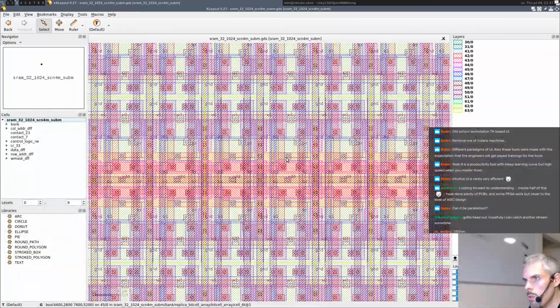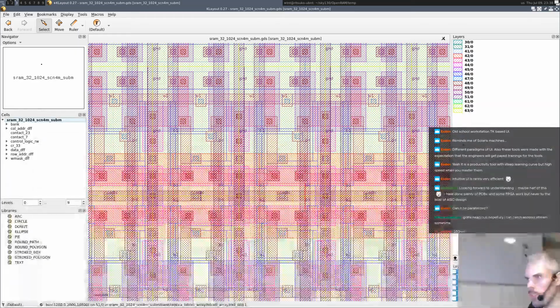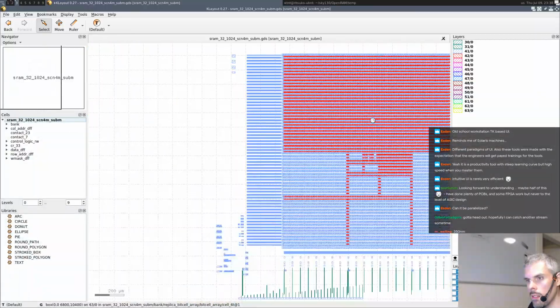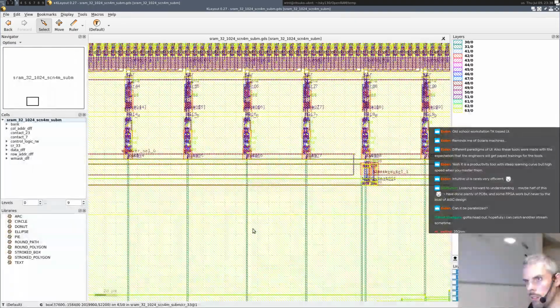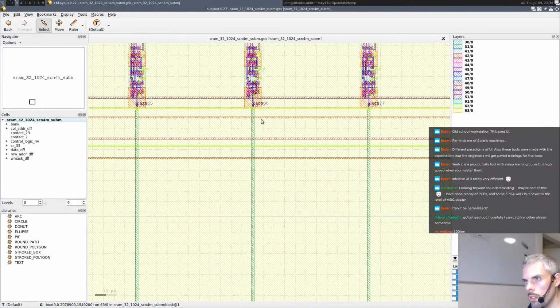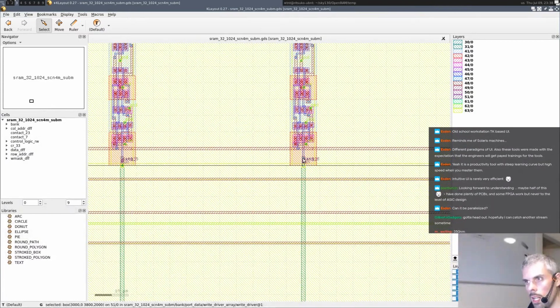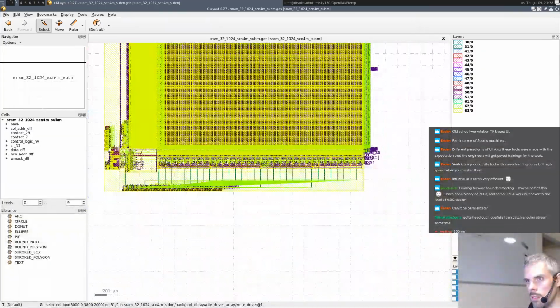So the layers that I used in OpenRAM are not the same, because, as I said, I didn't target the Sky130 technology because it's not supported at the moment. So I can't load layer names and stuff like that. But that's a SRAM generated for you. If you zoom, okay, it's barely readable because Layout is terrible at displaying text, but you have the data output pins here.